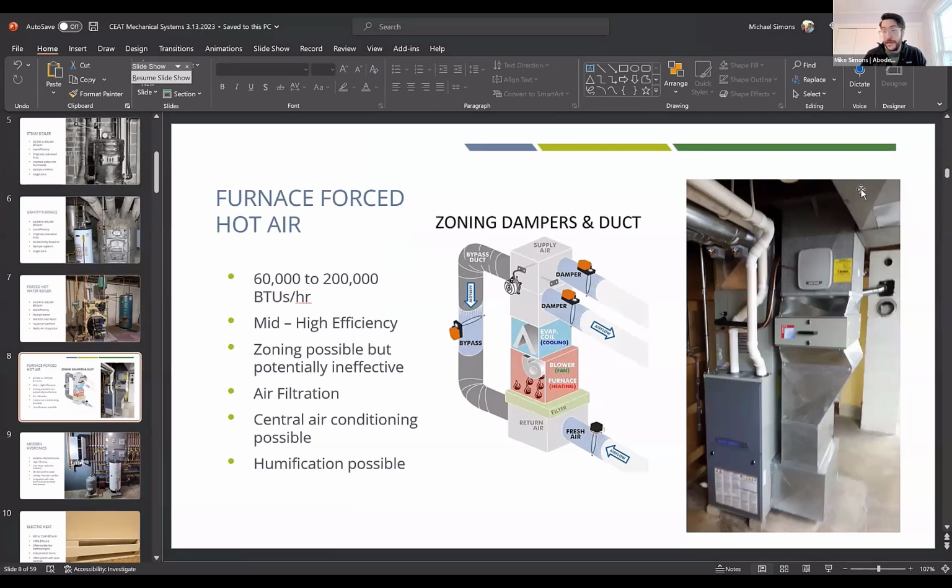You could just have the same Honeywell thermostat that we just saw on the previous slide. We could just have that communicating directly over to the zone controls over here, and that thermostat would be having primary and secondary terminals, and the primary would be the heat pump that's sitting directly on top of the furnace, and then the secondary would be the gas furnace. So the changeover can happen instantaneously.